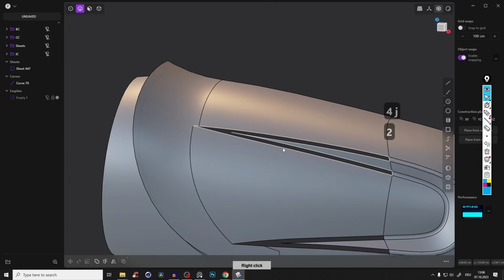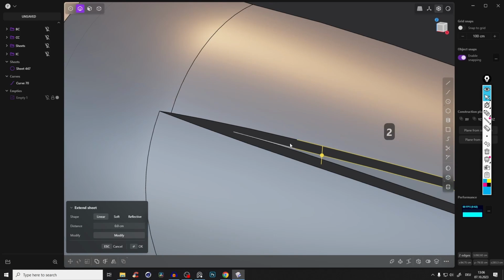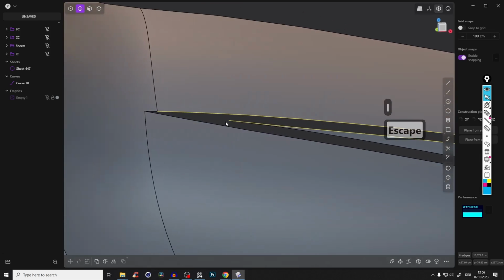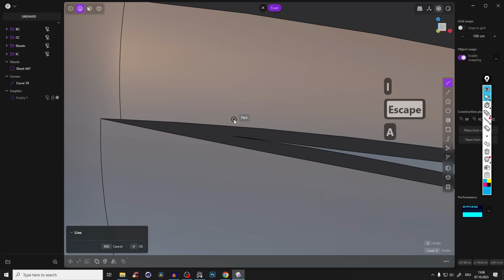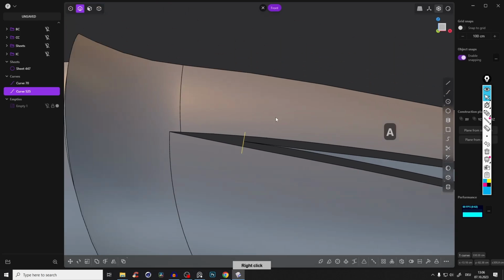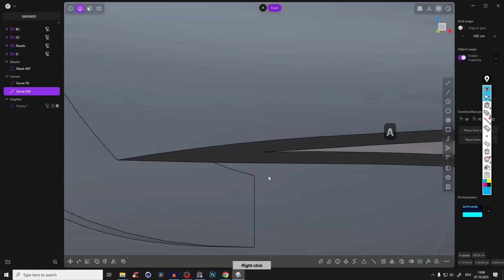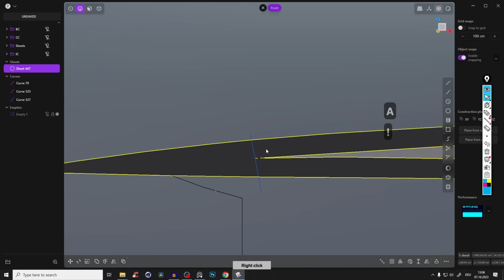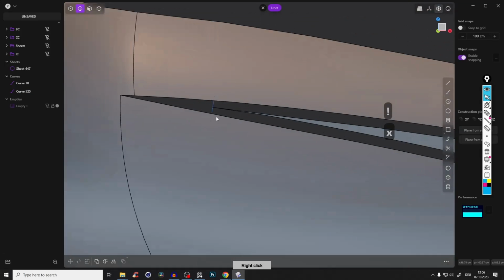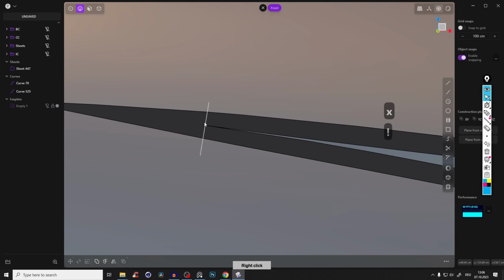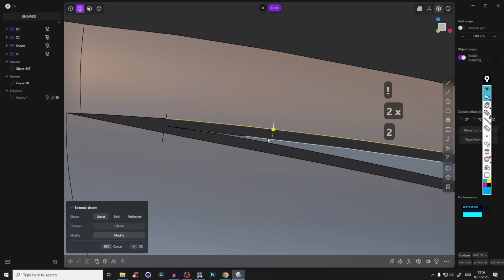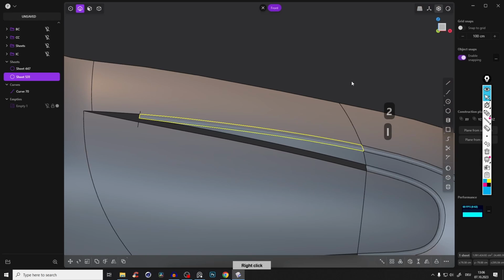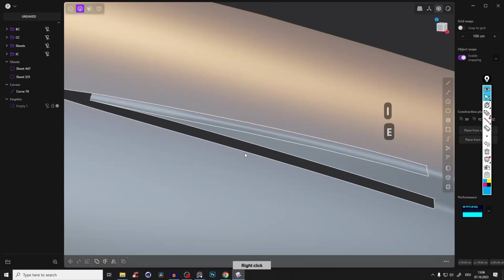And now let's do it here. So here we can't loft it this way, right? Because we have this extra thing here. So what I will just do is create here again with Shift A a line, and the same here where this triangle ends. And now use this curve with Shift 1 to imprint extra edges here, and the same here. So use this Shift 1 imprint on the surface, and perfect, because now we can take those edges here and you see, loft them and shift click it here, and you see we get the perfect transition.